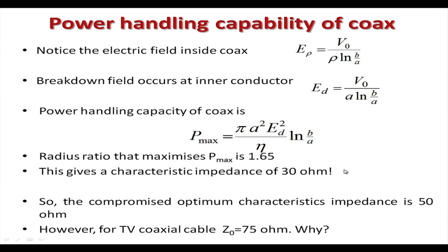If you do not want to use any other dielectric, that means for the air-filled case, this is the story. Here one thing I want to say: generally a coaxial cable's characteristic impedance is 50 ohm, but TV coaxial cables are not 50 ohm, they are 75 ohm.